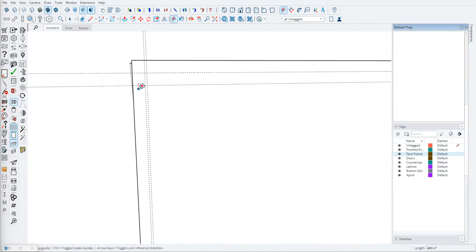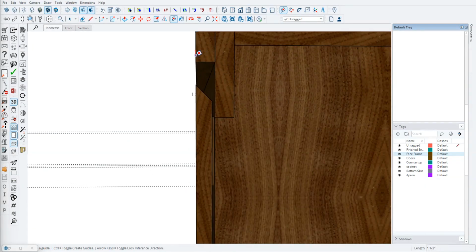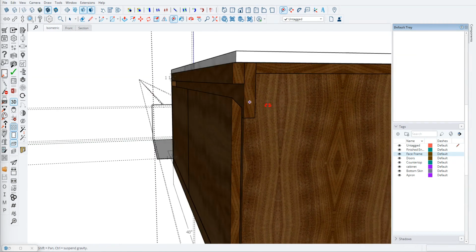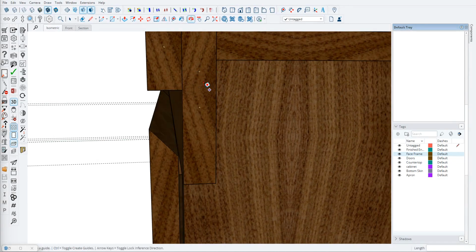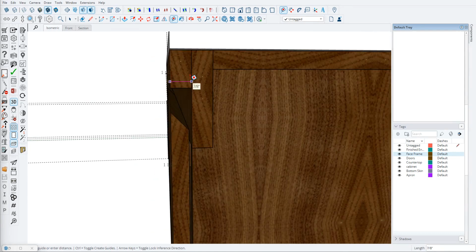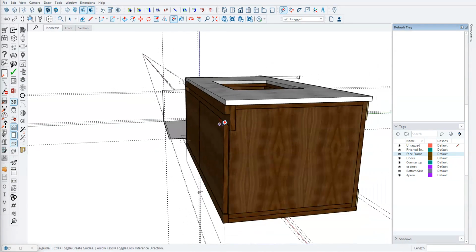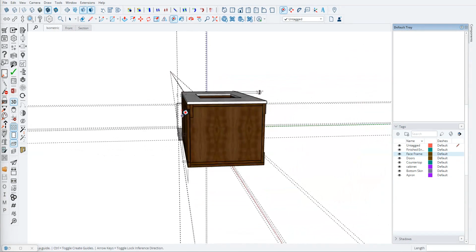So the 1.5 top rail is the full 7/8, right? Because it's going to flush out to the face of the door, but it's going to make up for the 1/8 bumper on that gap there. And then this right here, that is also 7/8. I don't know why that's 7/8. Maybe I just made that there. Yeah, it could be 3/4. Oh, maybe because I was using solid wood. Either way, that could be whatever you want it to be.